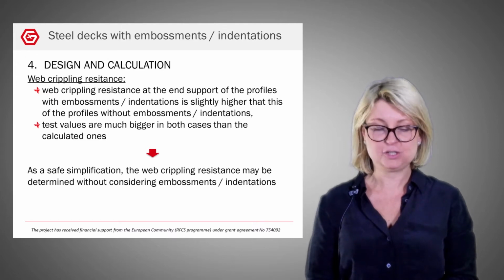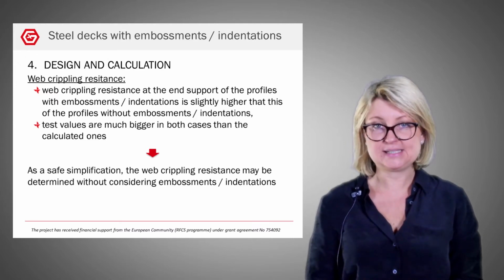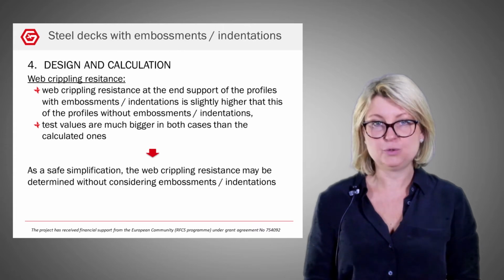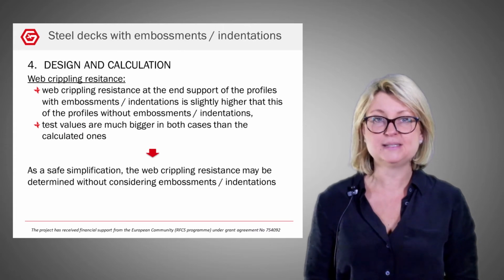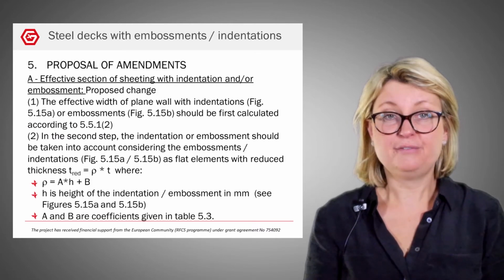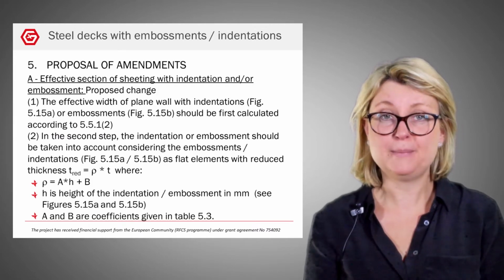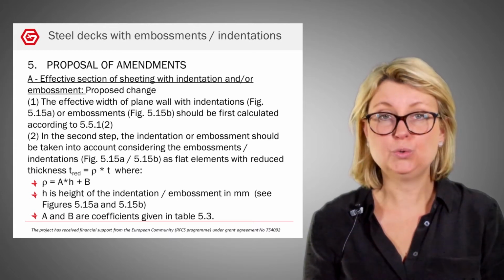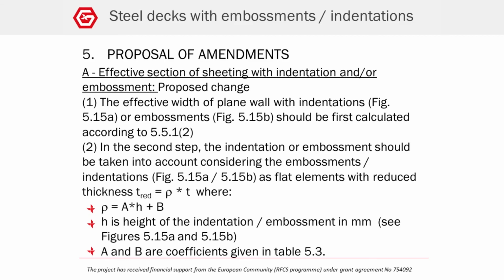As a simplification, the web crippling resistance may be determined without considering embossments and indentations. These results have allowed us to submit 2 amendment proposals on Eurocode 3 1-3.